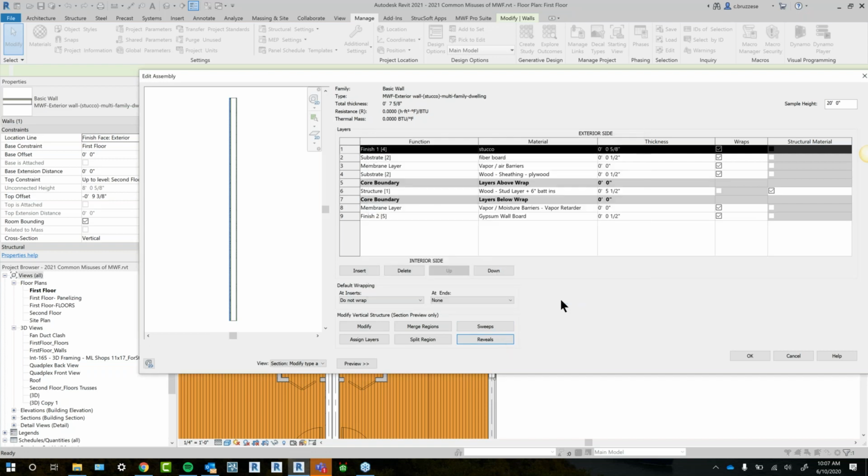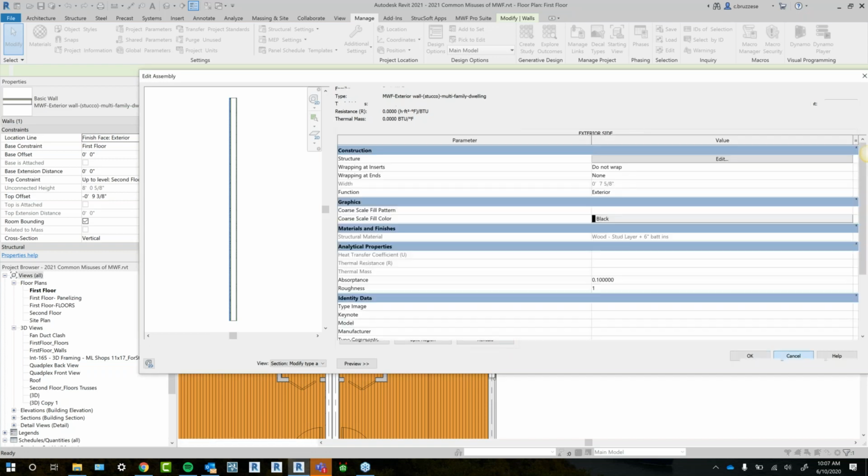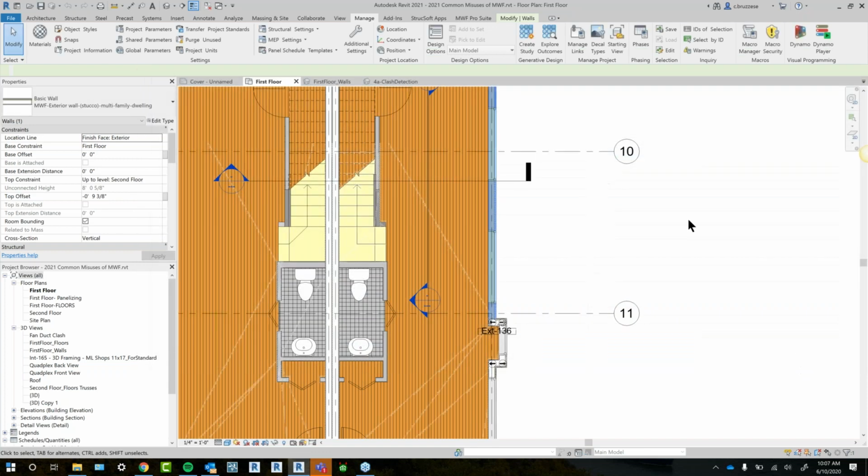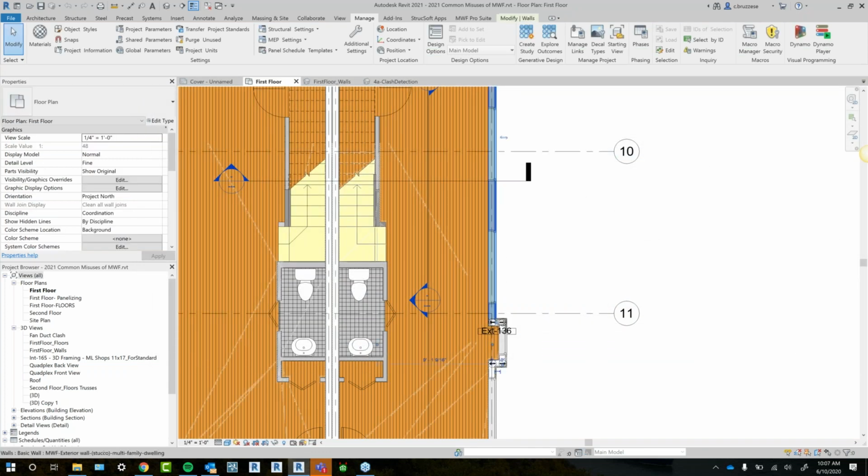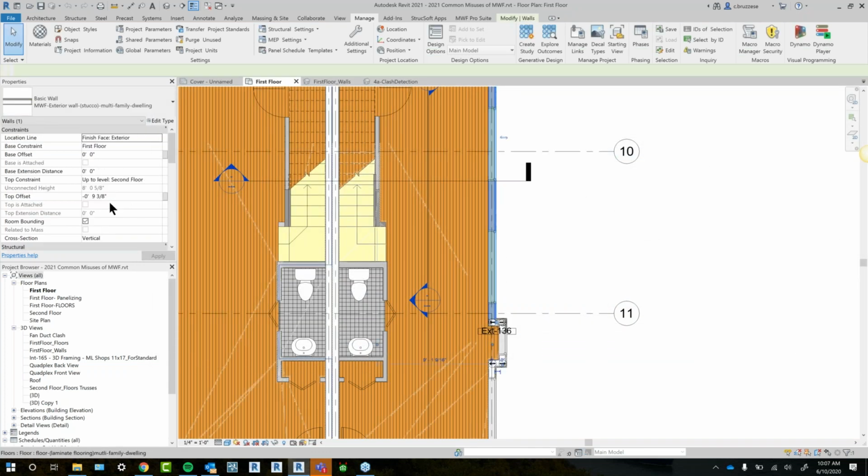And then other little things in Revit that we talked about in a previous webinar. So just things like your wall geometry, make sure that your top constraint is set to the right height, because basically this is what the panel will follow for the height, the length. It just follows the Revit wall itself. So just make sure that your profile for the wall is set up correctly.